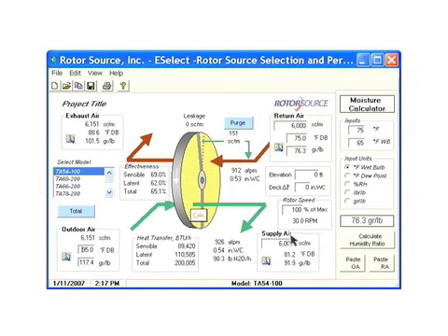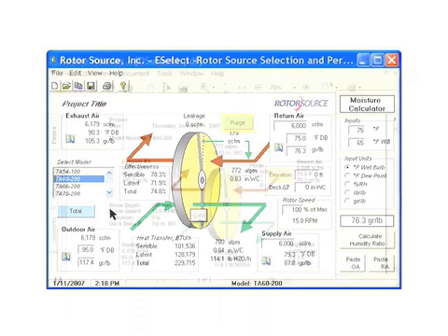In this case, the model selected was a TA54. As you look at the recovery efficiency and the velocity, you can see that this is not a good selection. Increasing the model size by simply clicking on the next size model increases the recovery efficiency and reduces the pressure loss through the wheel. Additionally, other variables can be input and calculated using this application to help determine the proper selection and use of this product, including rotor speed, deck-to-deck pressure, elevation, and purge.